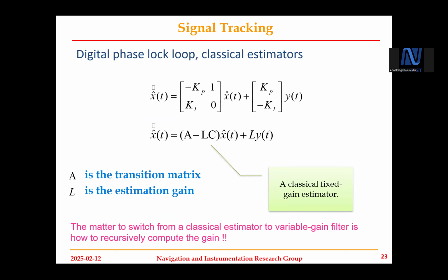But you will see some people apply a Kalman filter smoother, let's call it a smoother in this case, for every channel inside the GPS receiver. You track those variables for every channel. The tracking loops are something complicated inside the receiver. For each satellite signal, you need to dedicate one channel. In past hardware implementations, every receiver had 12 channels. Why is that? Because normally we would have, let's say, a maximum of 10 satellites available, right?